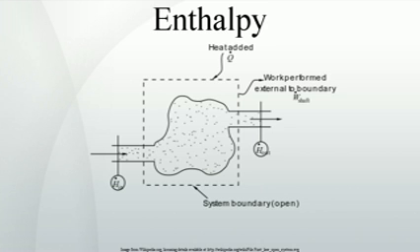This expression is described by Fig. 1. If we allow also the system boundary to move, for example due to moving pistons, we get a rather general form of the first law for open systems. In terms of time derivatives it reads: where the sums represent algebraic sums and the indices k refer to the various places where heat is supplied, matter flows into the system, and boundaries are moving.